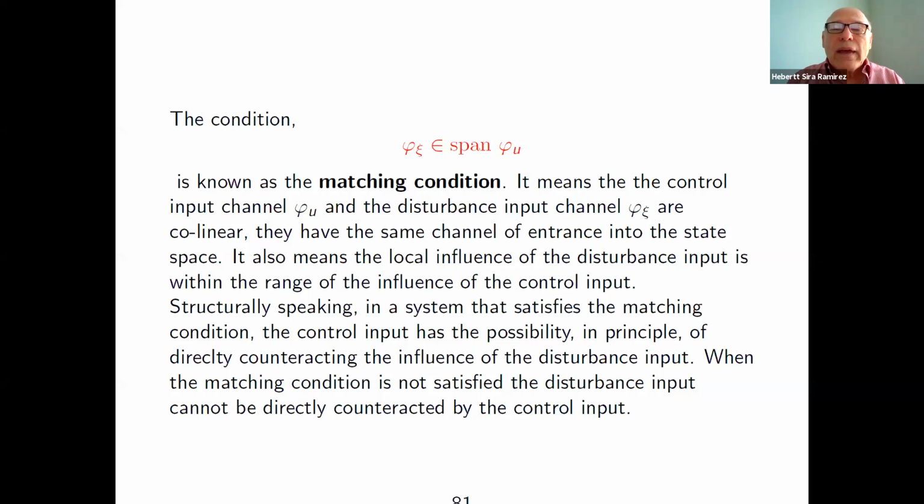approximately, of course, because you don't have a precise model, an exact model of the disturbance, and therefore a mismatch will always happen. Once you estimate that as accurately as you can, then you can include that in your feedback law in order to compensate, or to at least try to approximately eliminate, the effects of those disturbances in that equation that is the leading equation in the control of your system, because it contains the only place where the control input is affecting the whole ladder of the state variables that lead you to the output.